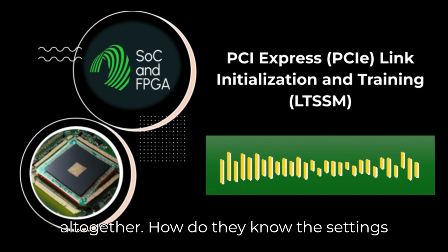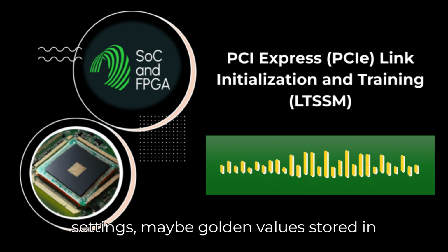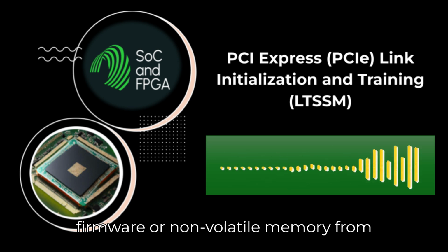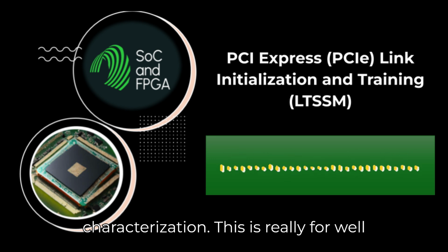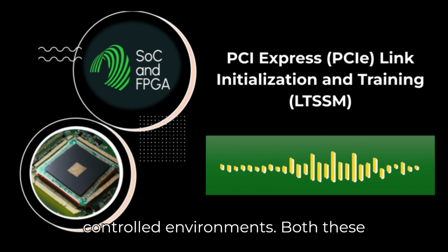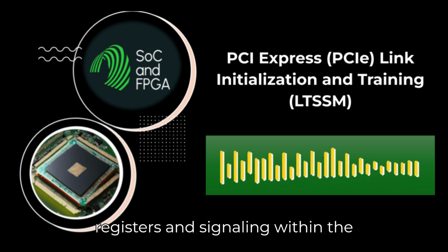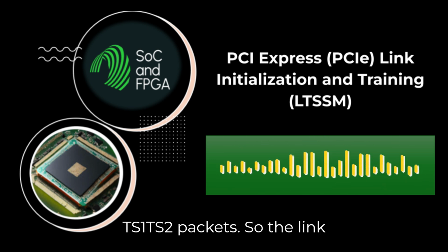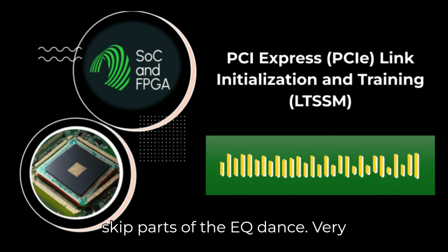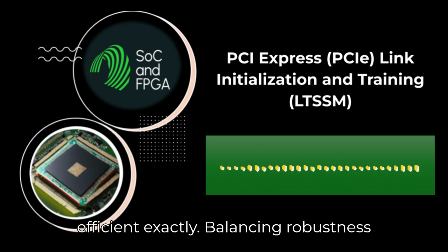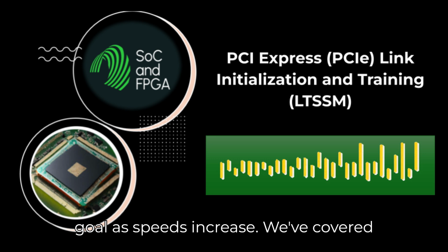Skip EQ altogether. How do they know the settings then? They'd likely use predetermined settings, maybe golden values stored in firmware or non-volatile memory from previous training or system characterization. This is really for well-controlled environments. Both these bypass modes are negotiated during the configuration state using capability registers and signaling within the TS1, TS2 packets. So the link can decide early on if it thinks it can skip parts of the EQ dance. Very efficient. Exactly. Balancing robustness with faster boot and wake times is always a goal as speeds increase.